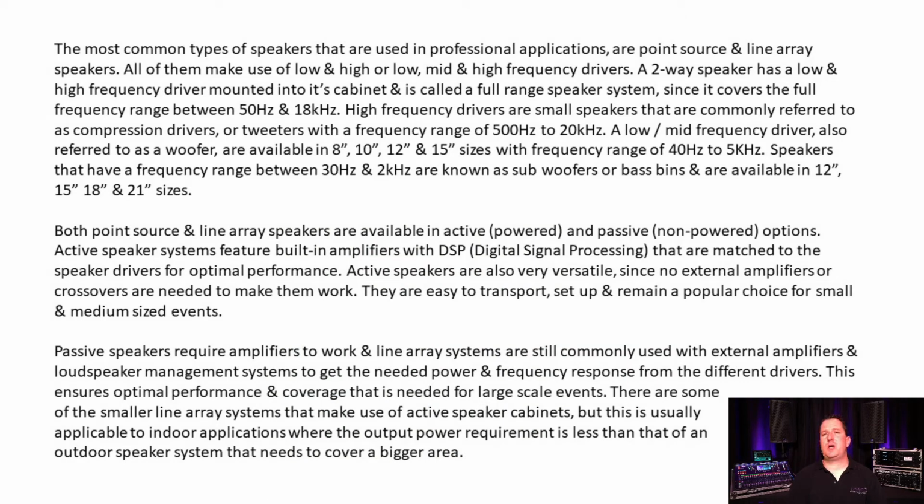The most common types of speakers that are used in professional applications are point source and line array speakers. All of them make use of low and high or low, mid and high frequency drivers. A two-way speaker has a low and high frequency driver mounted into its cabinet and is called a full range speaker system, since it covers the full frequency range of between 50 Hz and 18 kHz.